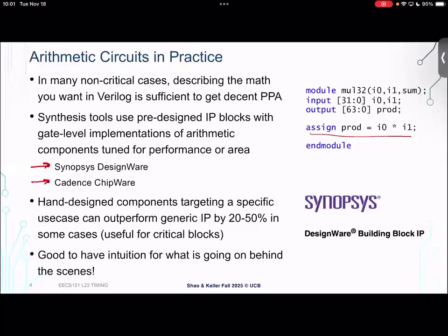How much more expensive is that? Well, we know from delay, if you're using a fast prefix adder, you're only adding one more stage, right? Because it scales with the log base 2 event. So having that intuition about how these things scale and how they're designed is super useful, even if you're not most of the time going to be doing the design yourself.